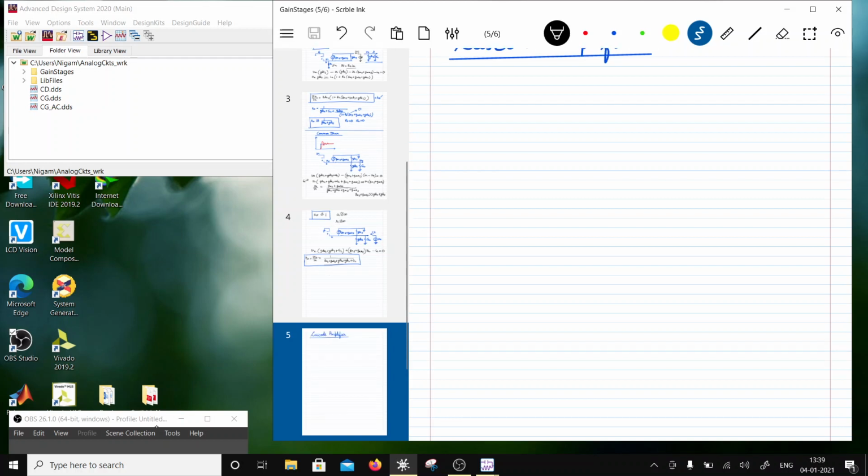So in this case the current mirror should have a similar load. Otherwise, if you put two loads in parallel, then the load is going to be smaller than the smallest. To avoid that, I'm going to use a wide swing cascode current mirror, which would look like this.